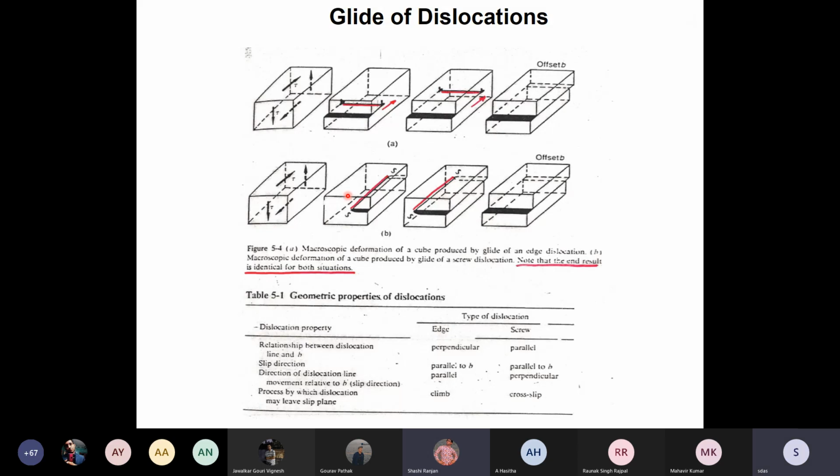You can develop certain alloys whose melting point is very high and whose diffusivity is low, meaning the rate of diffusion of atoms in that material is very slow. So you can minimize creep, but you cannot remove it completely. Generally these engine materials have a very high melting point.